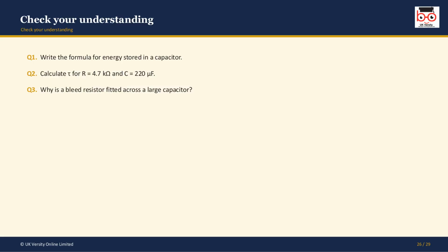Can you write the formula for the energy stored in a capacitor? Can you calculate the time constant for a 4.7 kilohm resistor and a 220 microfarad capacitor? And why do we fit a bleed resistor across a large capacitor? Give those a go.